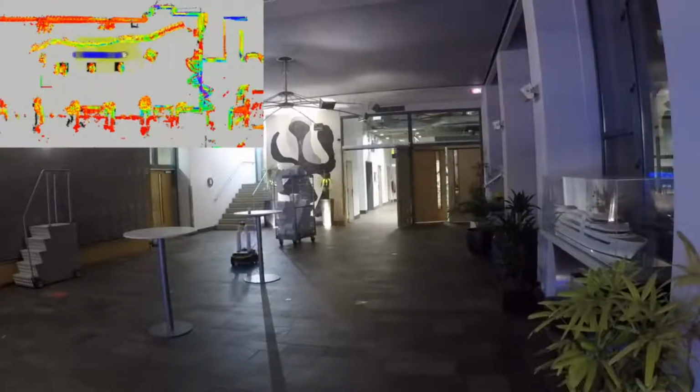reference path. We compare static collision avoidance to the ROS navigation stack, where the dynamic window approach is used for local motion planning. In this particular scenario, the dynamic window approach is not able to find a solution through the narrow static environment to keep following the reference path, while our method is able to deviate from the reference path to keep traversing the environment.